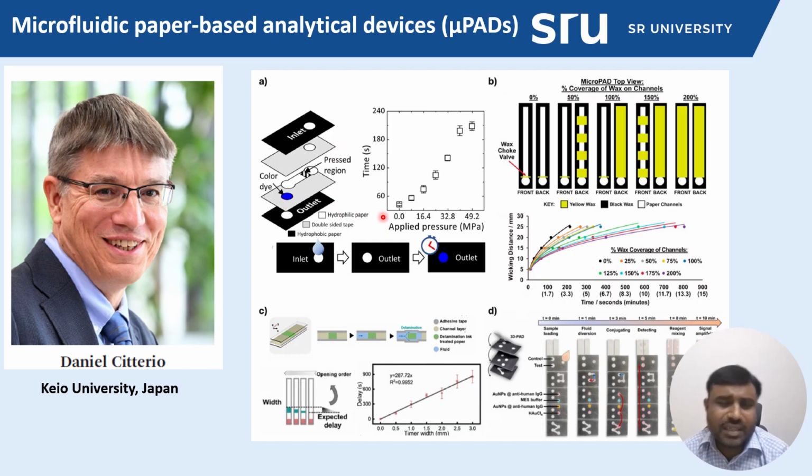This shows the electrode fabricating property, and how the sensor can be fabricated with different configurations of wax coating and channel. This acts as a channel. Here the black line is a wax curve. The interior white color is the paper-based substrate, so liquid can diffuse there. When adding a liquid, it diffuses easily within the channel, and the added droplet does not pass beyond this wax coating. This is the beauty of this paper-based microfluidic device.